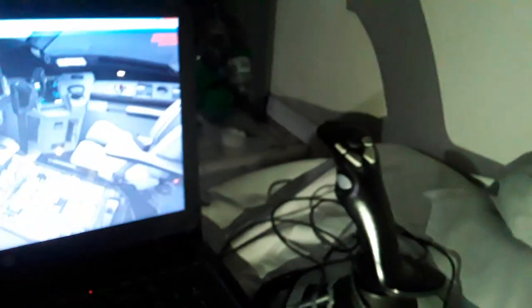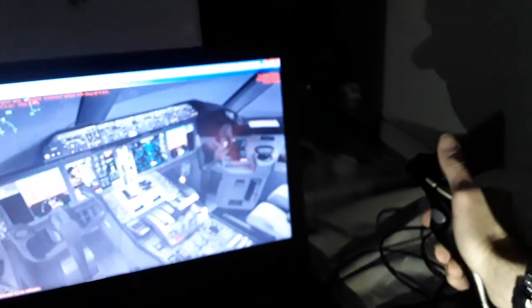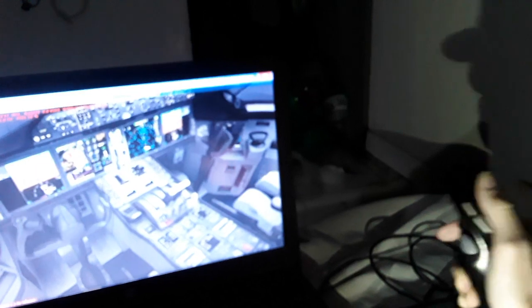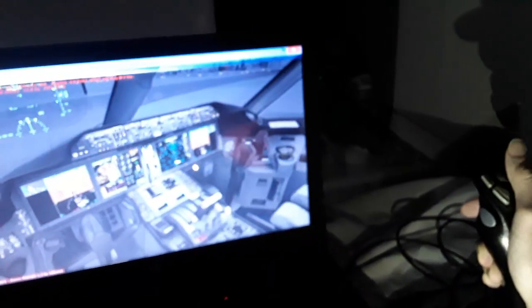So when we move the flight control, you can see we have flight control computers. It's an electrically controlled fly-by-wire system like the Airbus, but it also has hydraulic actuators to move the hydraulic flight controls around, like the tail, climb and descent, the ailerons, the spoilers, the rudder.